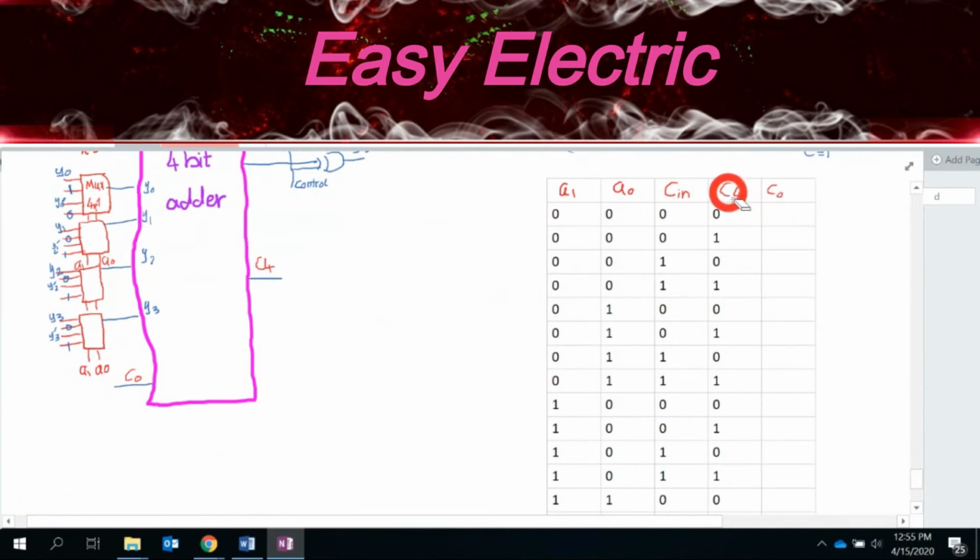So what else is related? It is related to C4 because whenever you have the subtractor, if you check the subtractor circuit that we discussed before, it's connected to the C0. So for that reason, C0 is related to these 4 variables, which I list here. And because there are 4 variables, each one could be 0 or 1, you have 16 different cases.